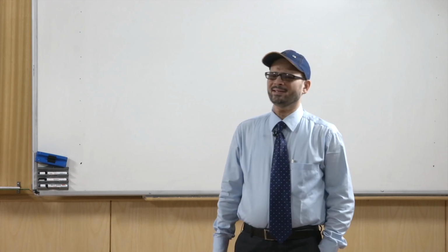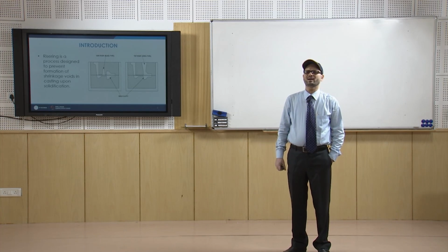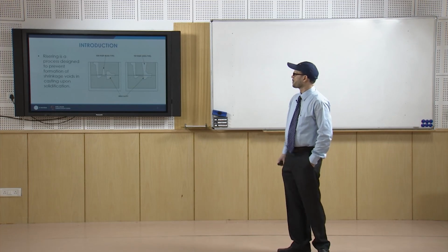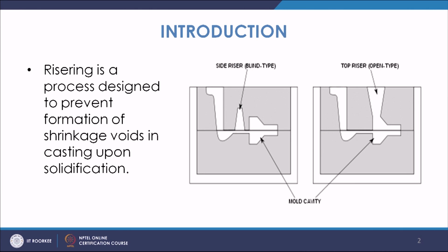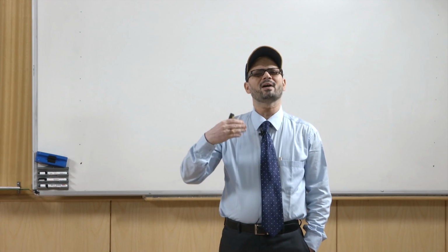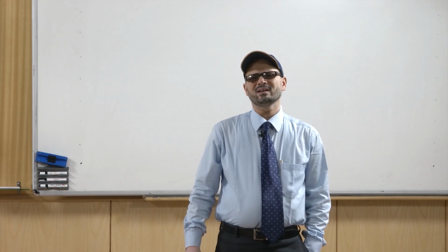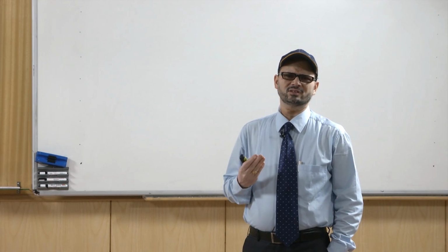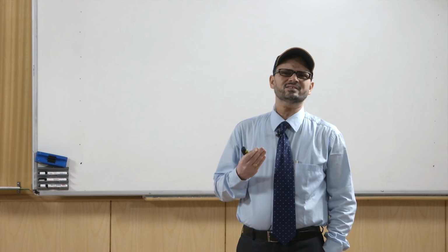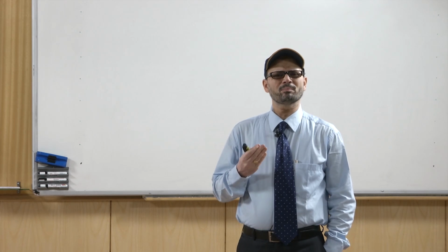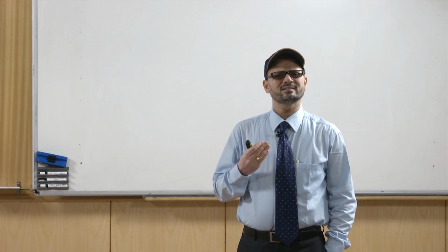So, why is a riser required in a casting? Risering is a process designed to prevent formation of shrinkage voids in a casting upon solidification. So, when the casting gets solidified, at that time there is the possibility of shrinkage in the casting, and this shrinkage has to be compensated by the riser.